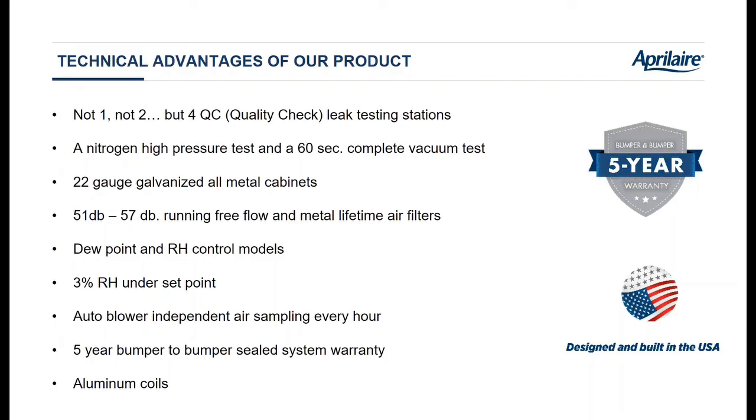We also pressurize it. And then, of course, to prepare it for adding the refrigerant, we have to draw down a vacuum. We draw down the vacuum to purge out the helium and the nitrogen. We draw down the vacuum to flash evaporate any moisture that might be in there. But we make it hold that vacuum for 60 seconds so we know that there's no leaks opening up under pressure.